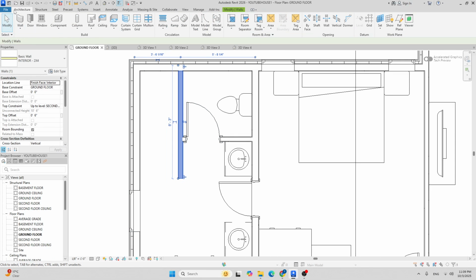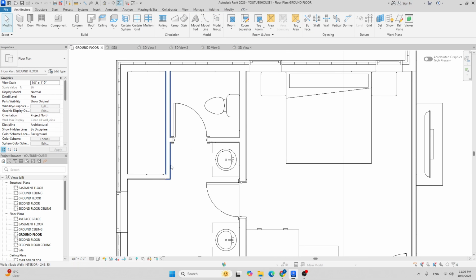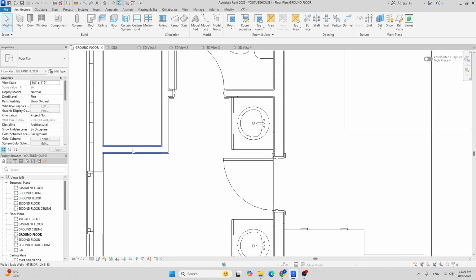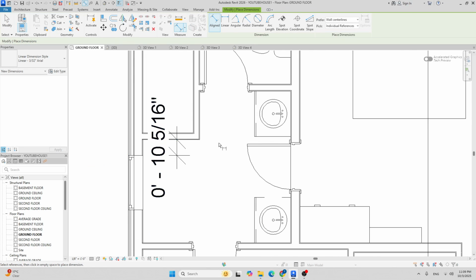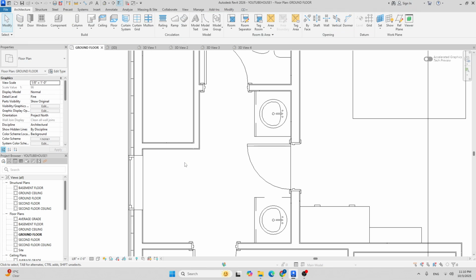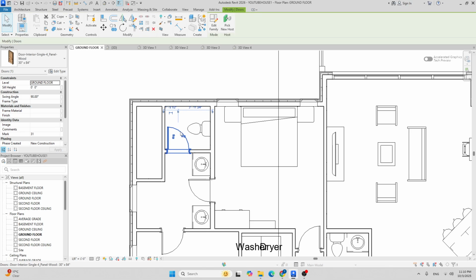and I will click this architecture wall. I'll click this one, go here, escape 2 times. And how big is this space? 7'5". I'll type DI, I'll click here, I'll hover over here, click here, click this one, and I will type 4". I'll delete this one, and I will click this one.